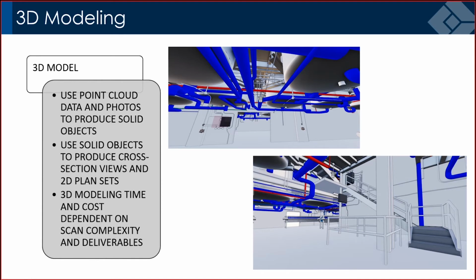The density of the point cloud when modeling is somewhat important, just to analyze the data properly, identify it properly, and full coverage as well. So when they're going out to the field and setting up their scanner, just know that they'll probably need a lot of coverage to really get the detail that's needed for modeling. Modeling also was a lot harder in the past.